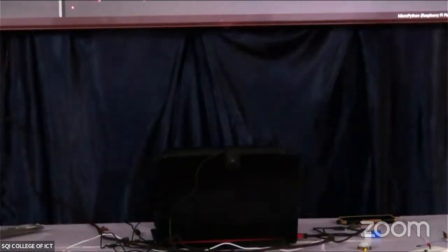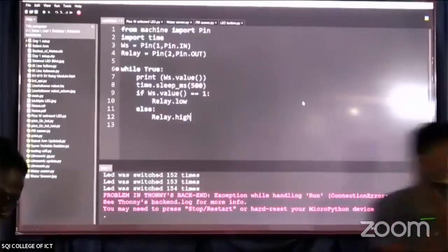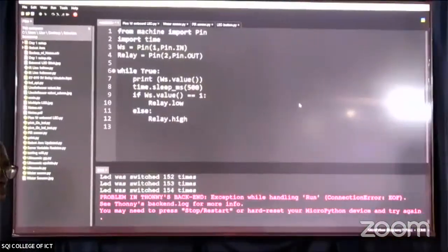That means I can incorporate this kind of system into a water tank. If I place my sensor at the top of a tank, and water doesn't get to the top of the sensor, the pump will not stop. Once water touches the sensor, I can trigger my pump off automatically without me turning it off. So we are looking at a system that can complete entire functions.